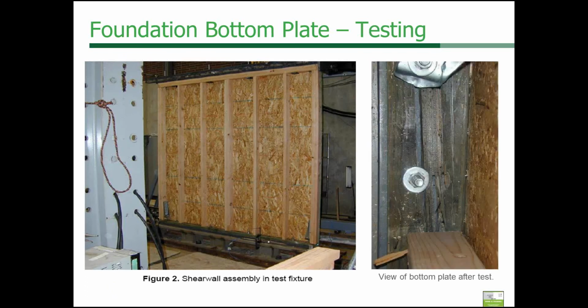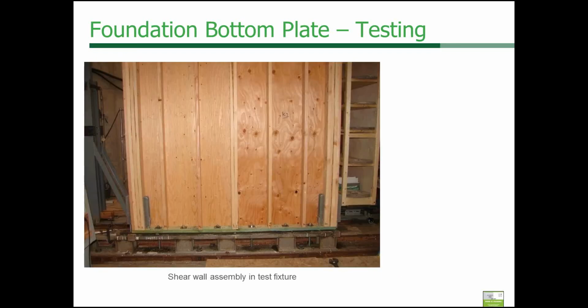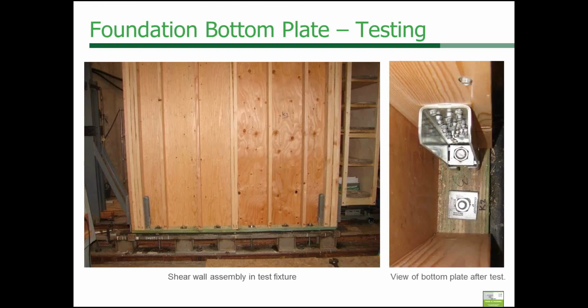They tested 50, I think, quite a lot of shear walls, and came up with, and you can see some of the brittle failure in the sill plate, doing all types of configurations, all types of capacities, and they determined that the plate, that square plate, was the answer to preventing that type of failure.